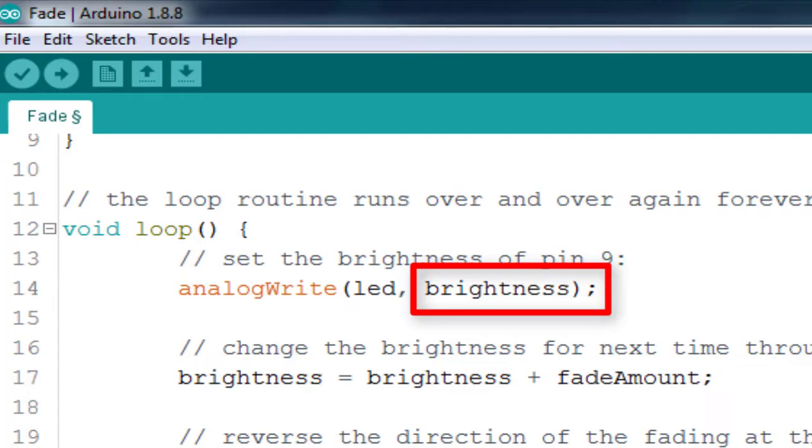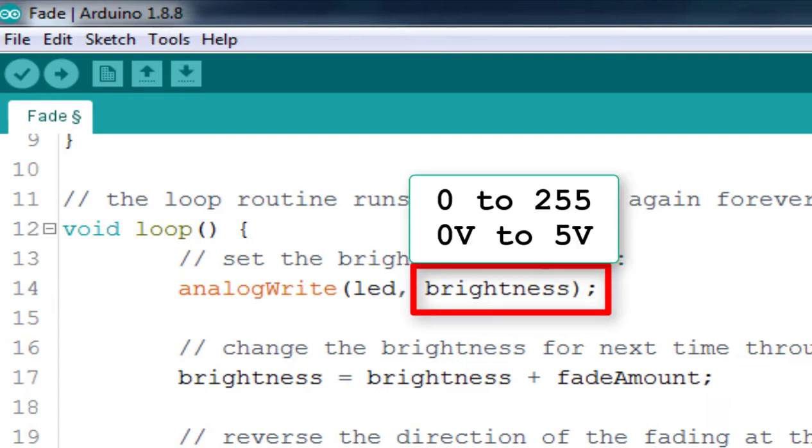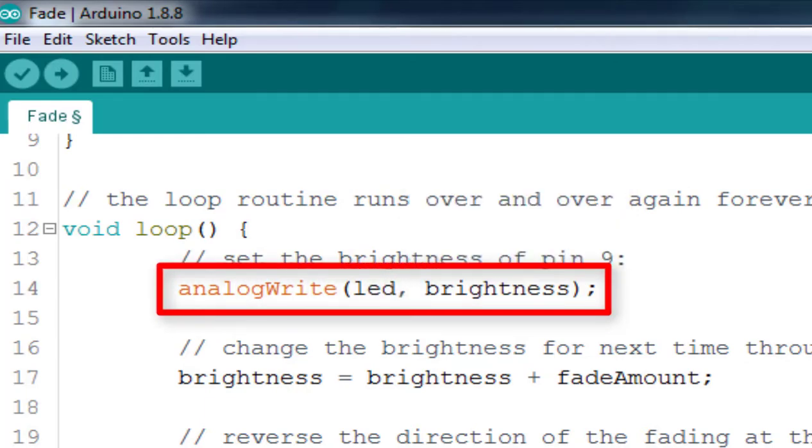The duty cycle specified for the analogWrite function is not a percentage, but a value from 0 to 255. The value 255 creates a 100% duty cycle signal, and 0 is a 0% duty cycle, generating a positive 5 volt analog voltage from the digital interface. The values between 0 and 255 scale the analog output voltage accordingly. So, the analogWrite function is just for the PWM output to the LED.